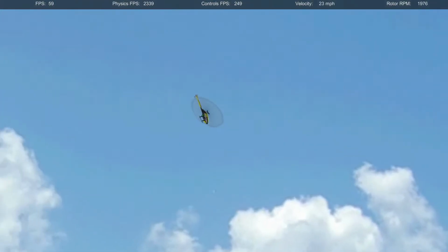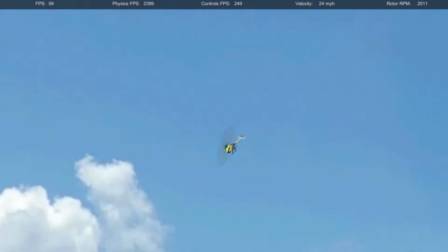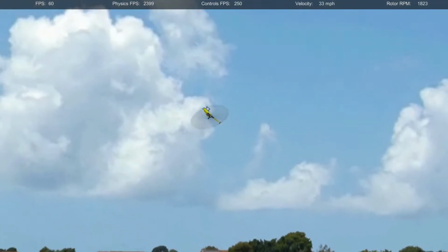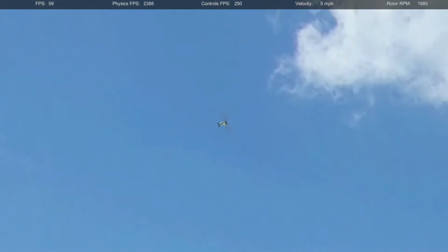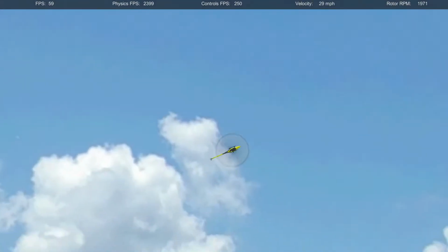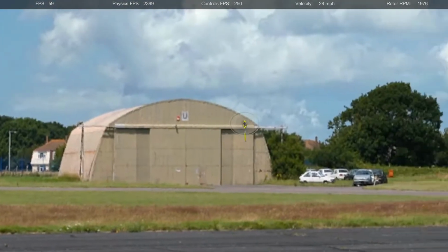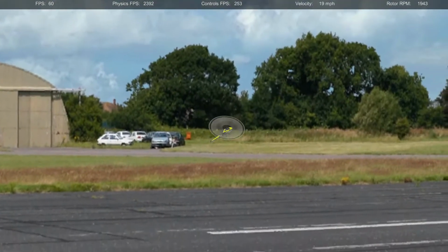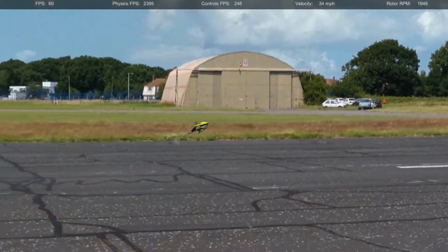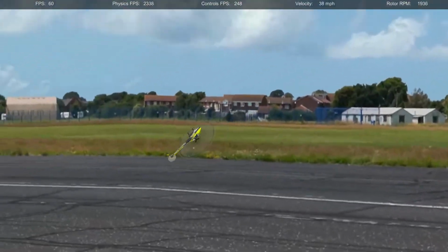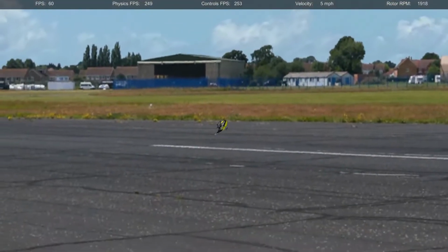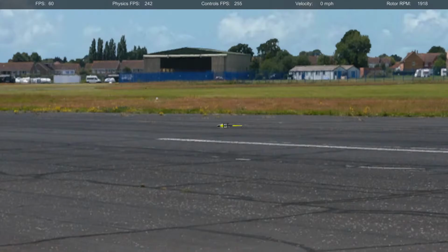You can manipulate drag at the wingtips to control yaw. Look at that picture of the B-2. You notice how the wingtips look fat? The reason is they've got their elevons split open in order to create drag. Why would you create a flying wing in order to save energy and then create drag while you're cruising? Or you can do what birds do and manipulate thrust at your wingtips to control yaw.